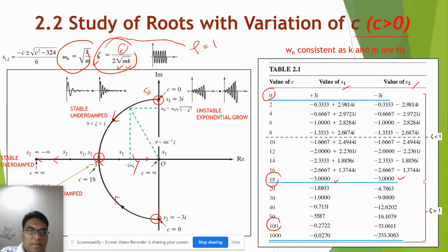When you get this plot, you can interpret it and know how the system will react. Basically the plot is only in this area, so your system is stable, of course, because we have damping. When we include damping, no resonance phenomena will happen, because the damping will absorb the vibrations.